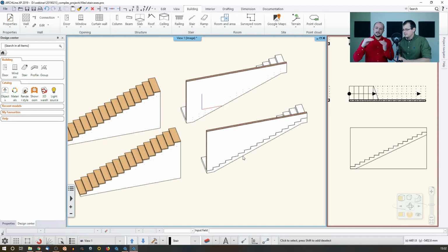For example, when the staircase changes inclination, because the left-hand side is based on a rule setting, it automatically updates itself until the wall can reach the staircase. The right-hand side is a custom-tailored drawing that you have created, so it won't automatically follow the changes when the staircase changes inclination, but you can update the profile by simply repeating the same step and then just joining them together.